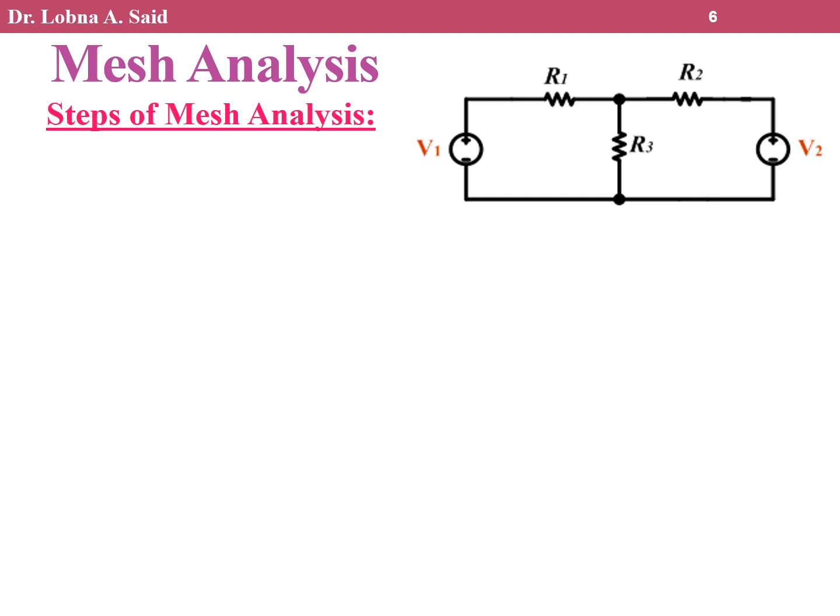Let me ask you a question. If I'm going to solve this problem using nodal analysis, where should I put my ground? I should put my ground here. Why? Because this node will be V1 and this node will be V2, I mean known, and this is the only unknown node, so I will have to write a single equation to identify the unknown voltage. Very good.